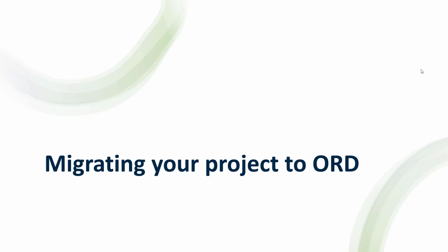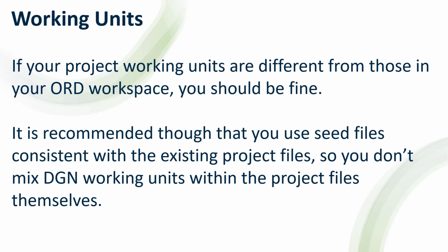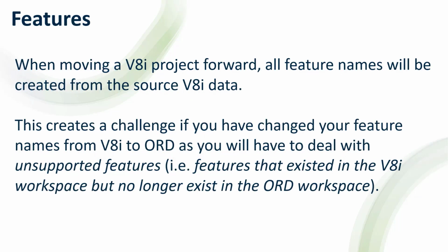In this presentation, we're going to be looking at migrating your project to OpenRoads Designer. There's a couple of preliminary issues that we want to deal with, and the first one is working units. If your project working units are different from those in your ORD workspace, you should be fine. However, it's recommended that you use seed files consistent with your existing project files. This way you won't be mixing DGN working units within the project files themselves.